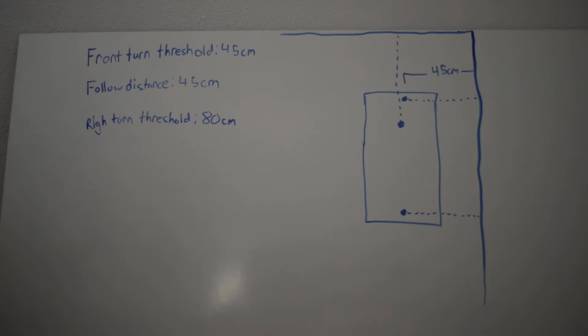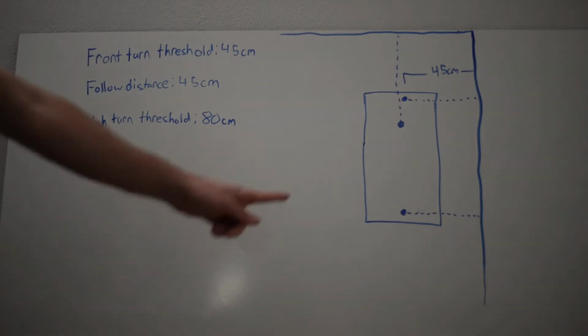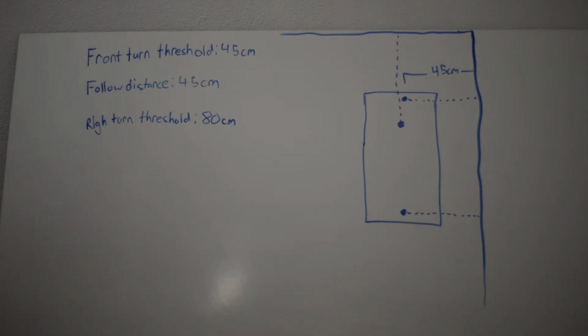The algorithm's role was responsible for reading in sensor values and sending out motor commands to navigate the rover through the map. Much of the algorithm's work pivoted upon a working wall-following algorithm. An early method of wall following involves setting the left and right speeds of the rover to certain values to always keep the rover turning towards a certain threshold distance. As you can see by this diagram, we chose 45 centimeters as our threshold.